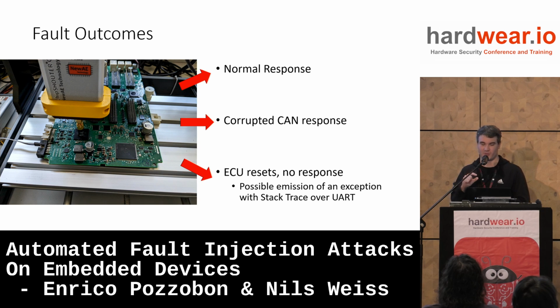So it's a small piece of code that you can write in your firmware that the processor will call every time an undefined, unexpected situation happens. For example, a division by 0, or the processor attempting to execute an invalid instruction according to the instruction set of the processor, or let's say the memory could not be read, or when attempting to read the memory, the CRC check failed.